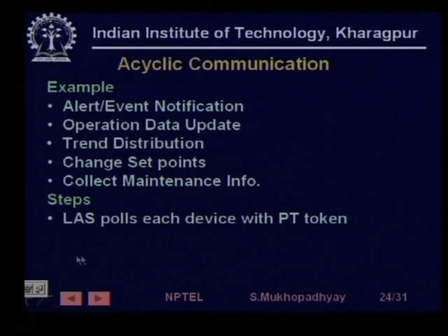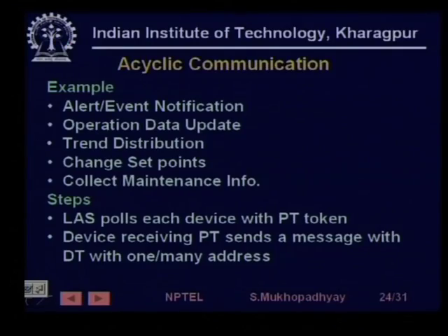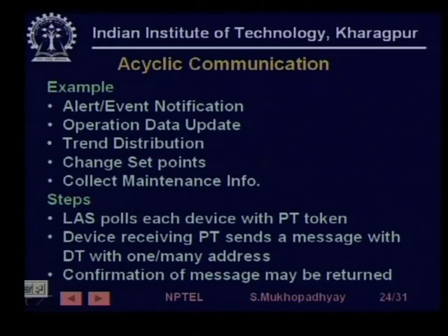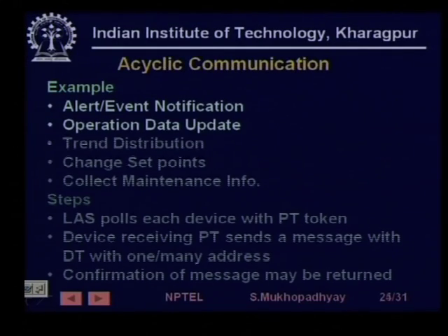For this, the LAS polls each device with a PT token. PT is a pass token. So, if a device has something to communicate, it will take the pass token and then communicate. If it doesn't have anything to communicate, it will simply pass the token to the next device. So, whoever needs it will hold the token and then transmit the data.